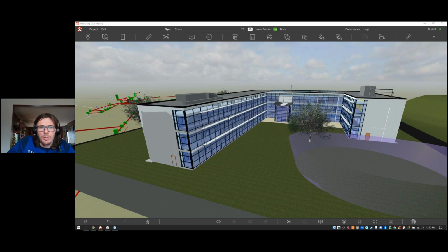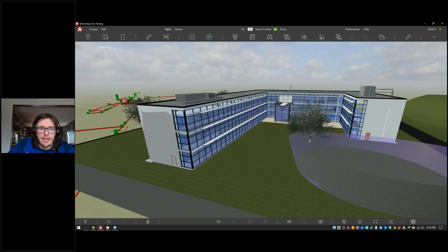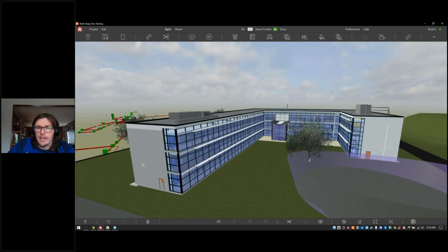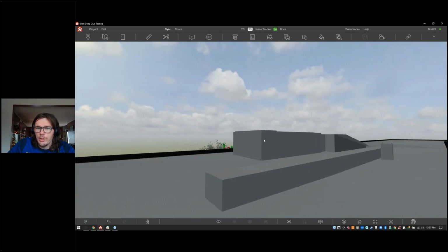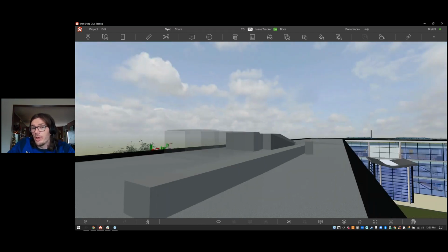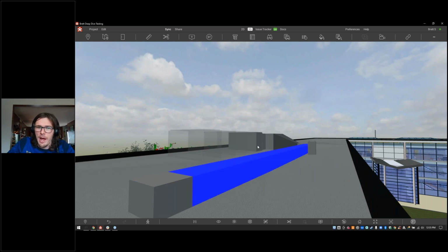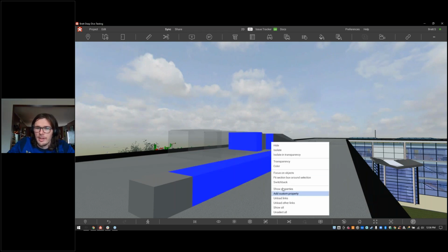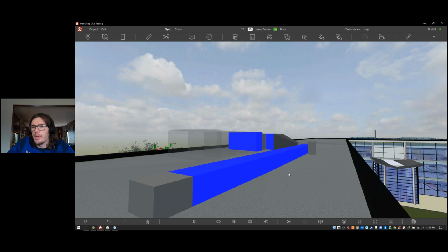All right, so in here, Helio looked like he had a few audio problems, but looks like that was figured out. We do have a question from David Crine here that says, can transparency be assigned to an object or a category instead of an entire link? And the answer is absolutely yes. So if we come in here, we can grab an individual object and actually control its transparency at 25%, 50%, or 75%, and make an individual object or an individual selection of objects transparent right from the right-click menu right there.